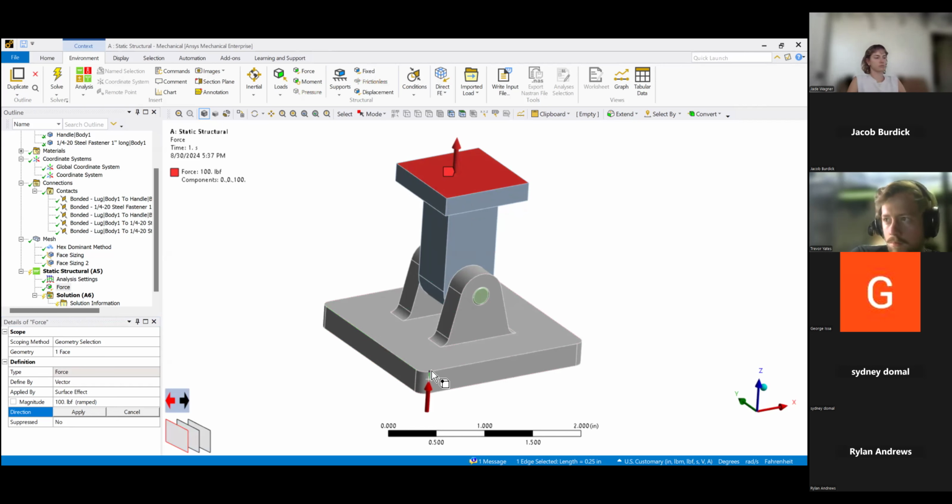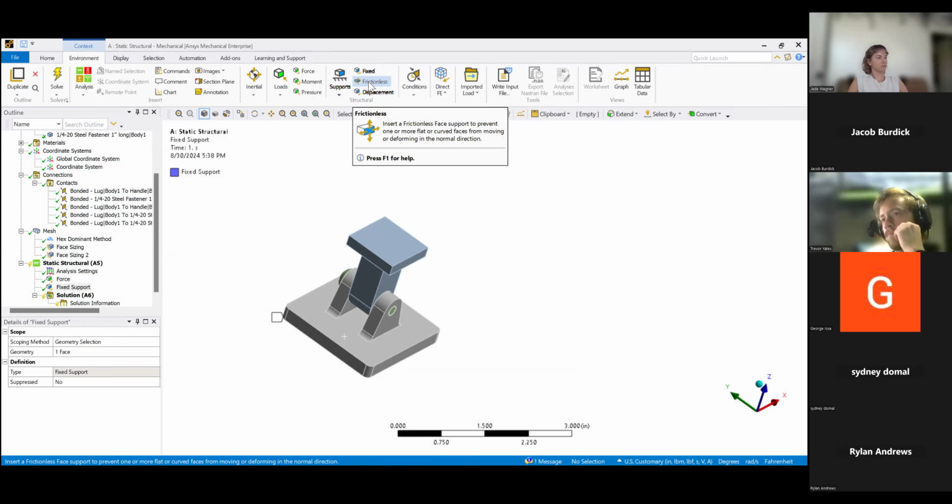There's different types of supports. So there's frictionless supports, and those are mainly used if you have a part in your assembly that you're not including in your simulation and you want to account for the contact of any part that is within that part that doesn't exist. Generally, what you want to do is put a frictionless support on it. You can put a frictional one, but I also don't recommend it. Same reason as with contacts. It produces nonlinearities in your studies, and that will affect your computational time and could possibly affect your results if you do it wrong.